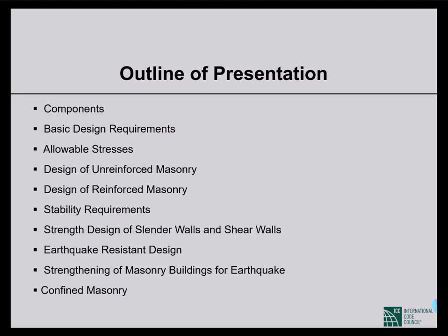So as I've mentioned in the very beginning in the basic design requirements, a basic assumption is that there is very small effect of eccentricity of loading. That is a basic design requirement of unreinforced masonry, and that doesn't hold in the case of this type of mixed construction, a mixed system of moment frame and unreinforced masonry.